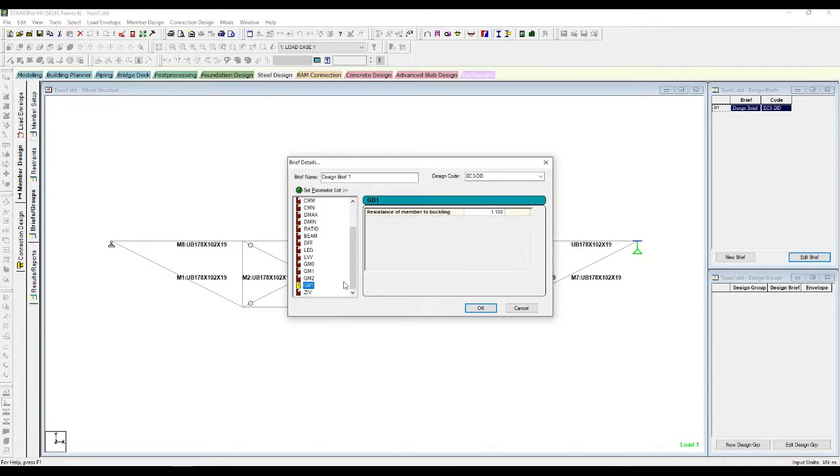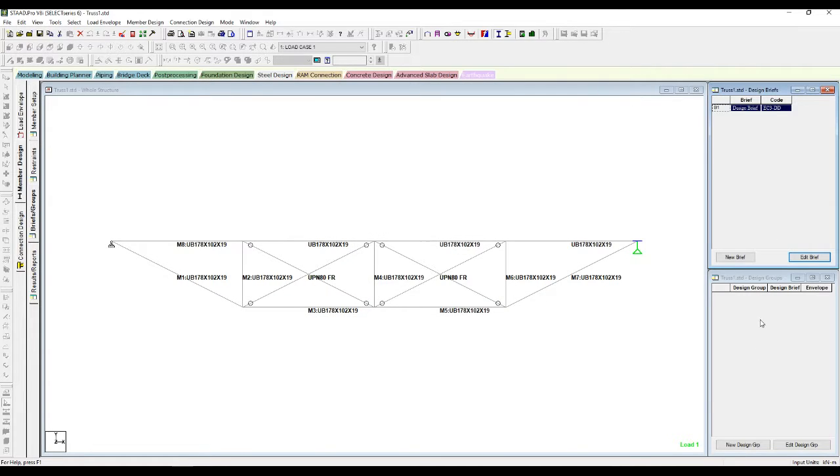And that doesn't really matter. There are some other parameters here. So if your ultimate tensile strength is different, or the yielding limit, if you want to define a different yielding limit of the steel, you can define it. If you don't change this, then it will take the parameters by default of the Eurocode. So I'm just gonna change those two, the gamma 0 and the grade of steel, because this is important, and that's it. Then we have to define the groups.